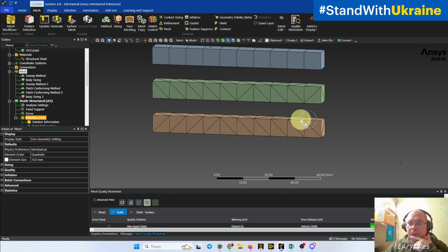They can be used even for stress calculation, but for explicit, for nonlinear tasks, you need to create a mesh which will have good stress and stiffness distribution with this linear tetra, and sometimes it's even recommended to use this linear tetra instead of nonlinear tetra.